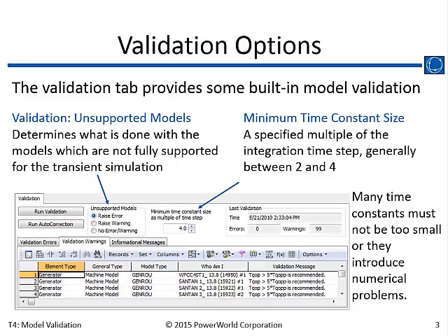So how do you figure out the time constant to begin with? I mean, do you have a random number between like 2 to 4 or something like that? Well, the time constants come from the model, so we're not figuring them out. We're just taking what comes in the model, and then we're looking and saying, is that value okay? And usually we're concerned about very small time constants that would cause numerical instability.